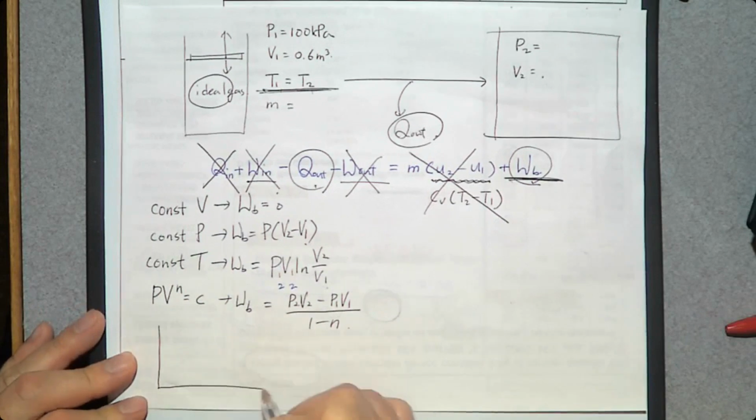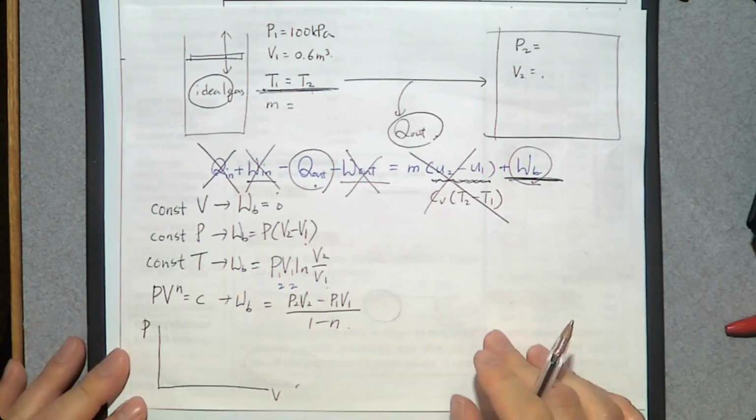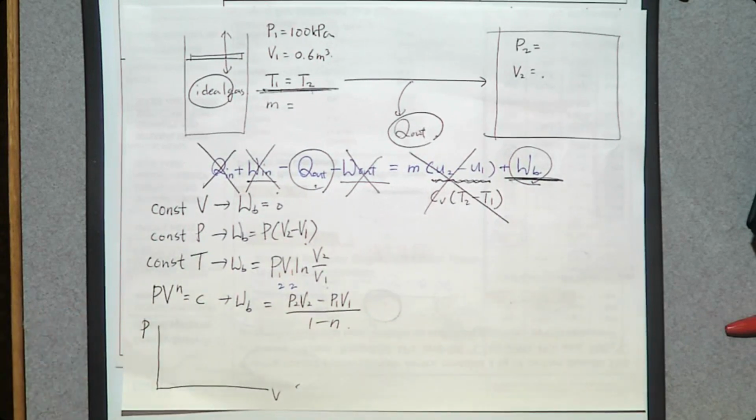And lastly, we can use the PV diagram, and we used this PV diagram for the previous spring-loaded piston cylinder device. And if this one is an isothermal process, moving boundary work is P1 V1 natural log V2 over V1.